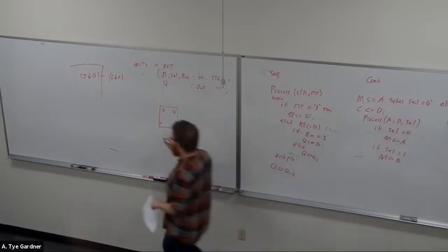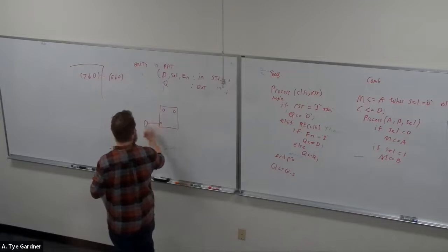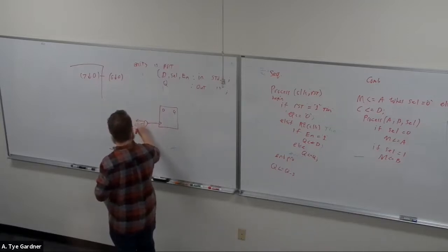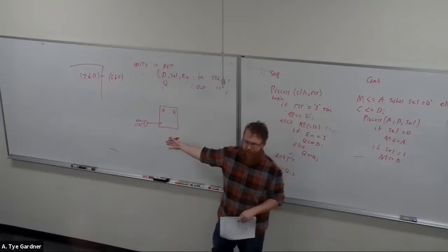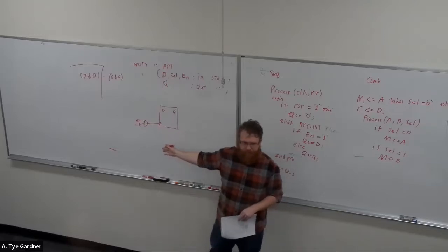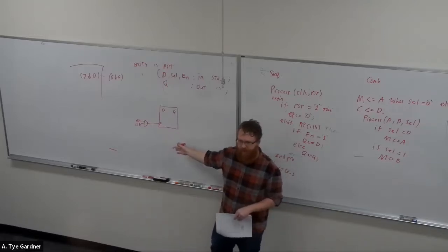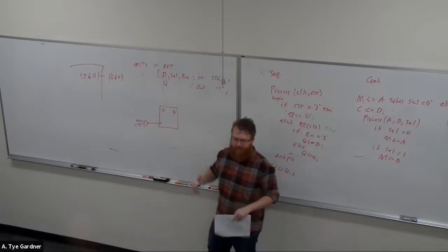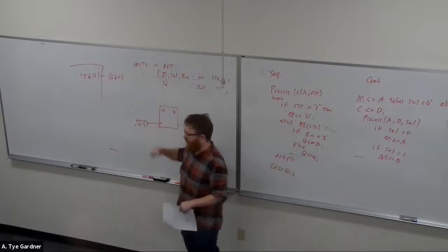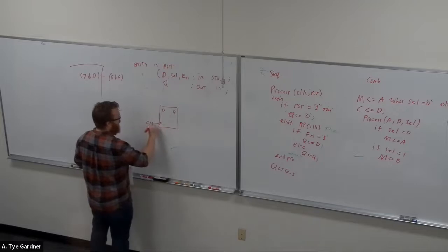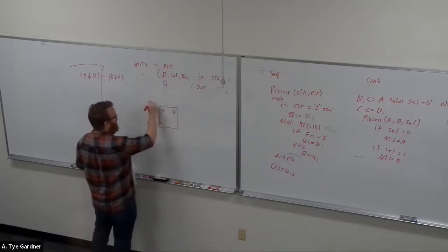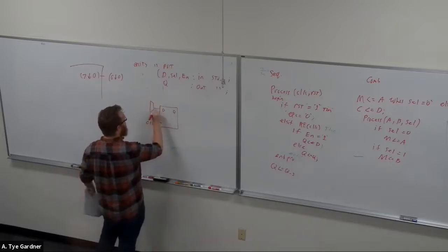So the wrong way is that, right? That is a clock enable, but it has issues. What are the issues? It doesn't know the difference between enable and the rising. Yes, it doesn't know the difference between a rising edge of an enable and a rising edge of a clock. It has no way of differentiating. So we don't like to do that. We just like to put the clock directly in. We do the mux, just like you pointed out.